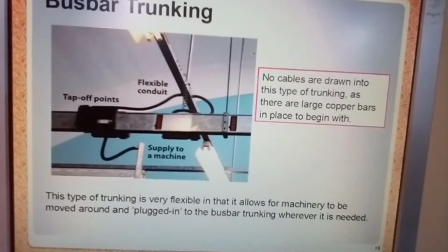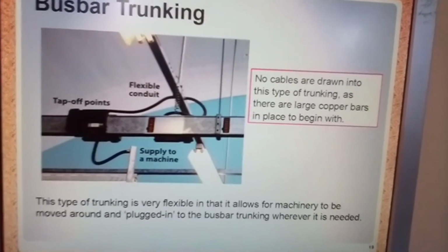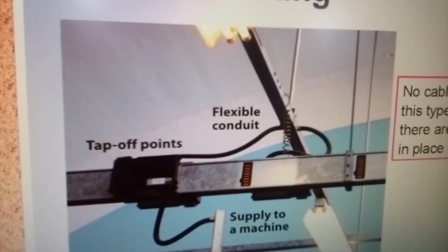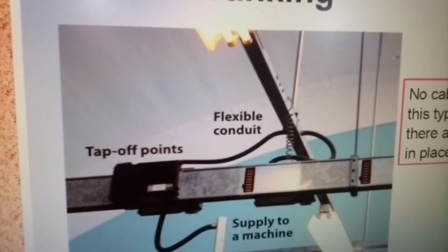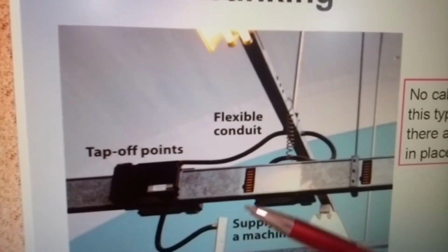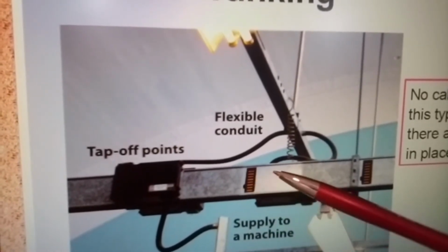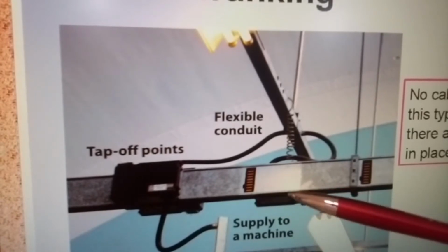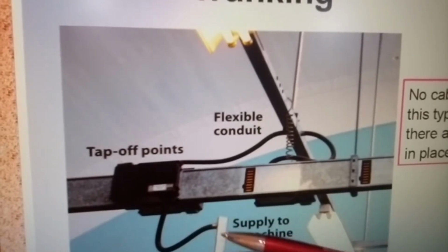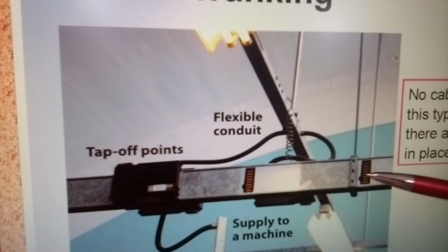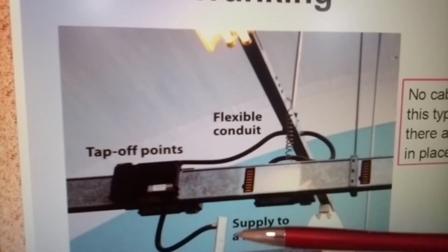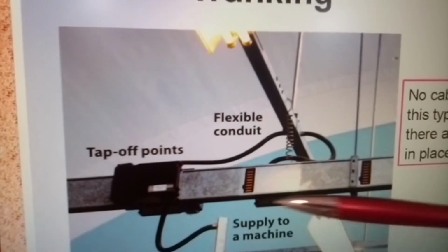And here you have your busbar trunking. Now let's get into this completely. So you can see this in detail. Here are your connections where your busbar would link into, the supply lines, and that would act as your supply to your machines. So you have your connections here. That one's connected to a machine, and this would be three-phase and neutral with earth systems.